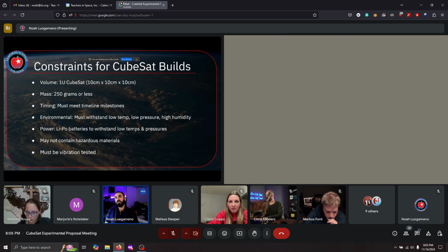That is really the thing that would most likely cause your CubeSat to cease working, just because it's easy for wires to come loose and whatnot. My recommendation is to use something like E6000, which is a type of hobby cement.